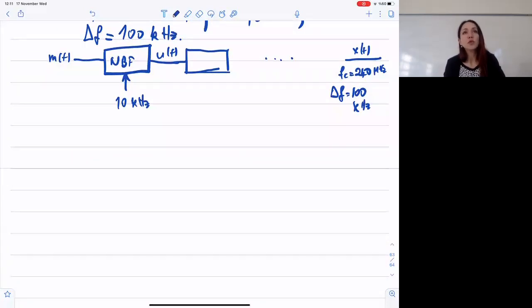Yeah, right. That could have been a phase modulated waveform as well. We commonly pick FM. Phase modulation is also a valid angle modulation type, but we saw that its bandwidth increase is faster with the input signal's bandwidth. So for that reason, and possibly several other reasons, FM is usually preferred. While we define phase modulation, most of the time we focus on FM.